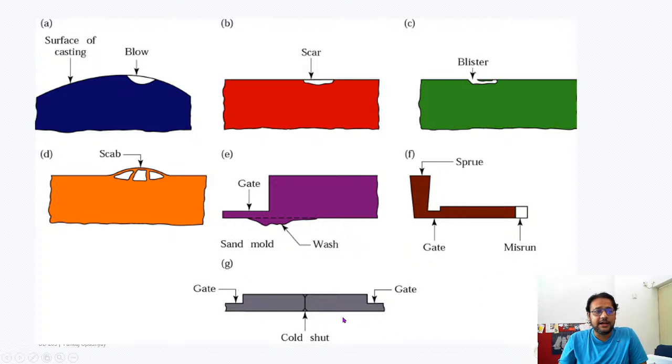And finally, let's say that there's a specific kind of design where instead of the molten material filling from one end only, you have 2 or 3 places where it fills up. So you pour from one end, and the gates are designed in a manner where the flow enters the cavity in 2 or 3 different places. Now imagine the flow of the material, it flows in, and at some point these 2 flow fronts, this is an important terminology, interact with each other.